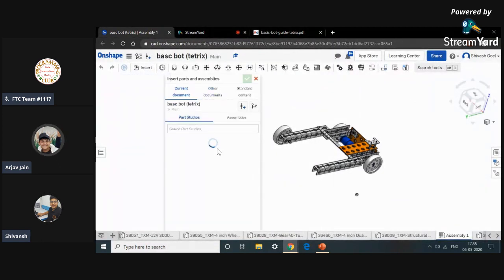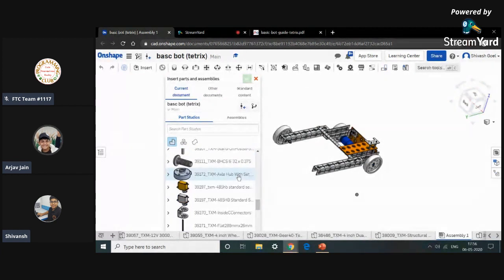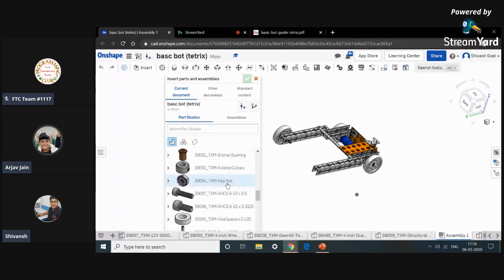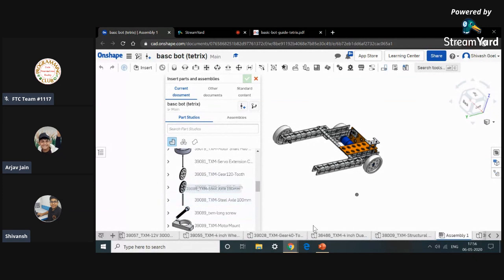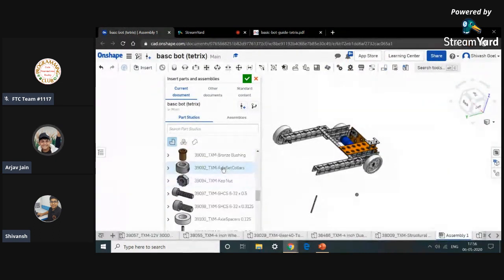Okay, so there is a question how to use the zip file in Onshape. Just open the zip file. When you open it, there must be a folder. Just copy the folder to another place in Photos or on desktop. Go to Onshape, click on Create, Insert Parts, and then you can select the copied folder.